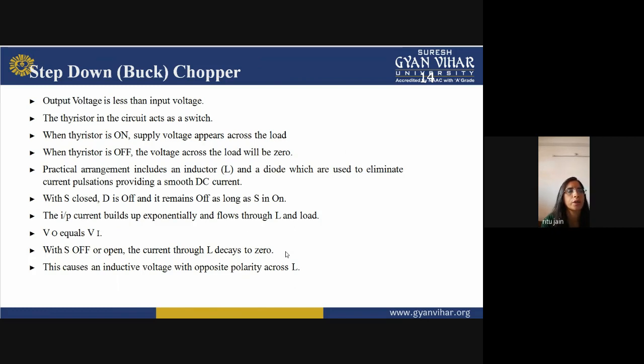So V output is equal to your V input. When switched off, the current through L decays to zero. This causes an inductive voltage which has opposite polarity across the L.